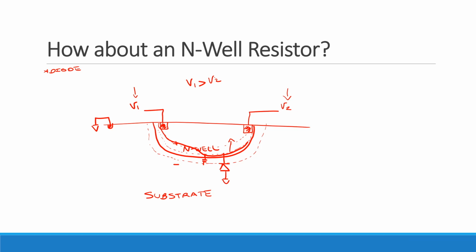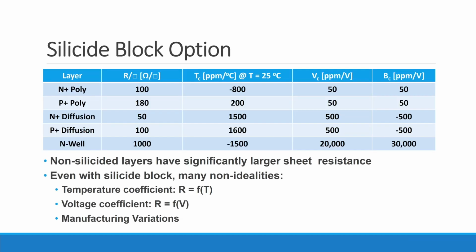And as you also hinted at, if I move this P substrate around, which is kind of implicitly over there, relative to V1 and V2, well, again, that's going to shift that whole profile around, okay? So bottom line, I can do it, but I'm going to have a lot of capacitance from that diode, and it's going to be highly nonlinear, just because the depletion region is going to change fairly substantially as I move those biases around. Okay? So, doesn't sound too great.